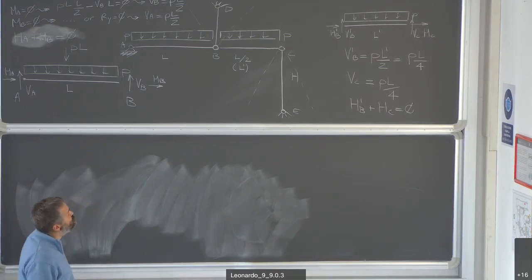Again, we have two members which are hinge-hinge. They are straight. They have no load applied. Basically means they are subjected to axial force only, okay? And this greatly reduces the burden of calculations for you.